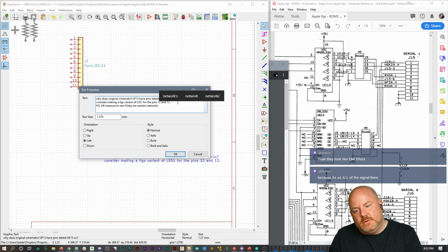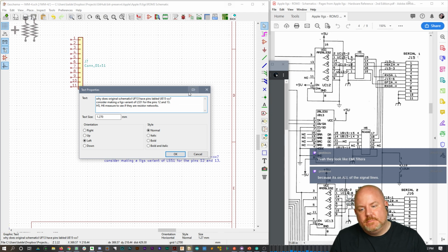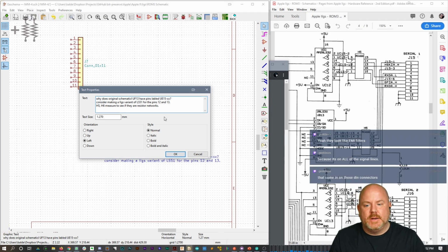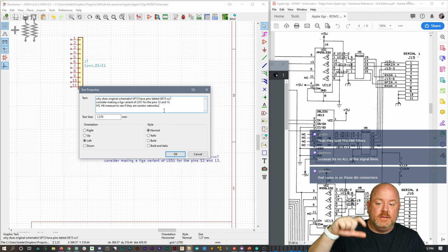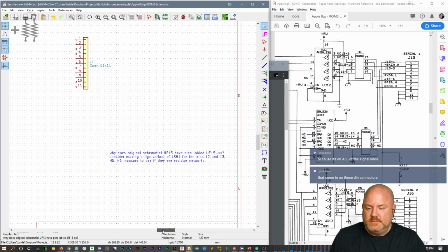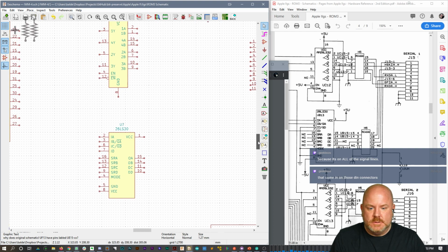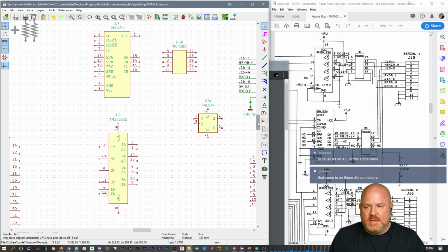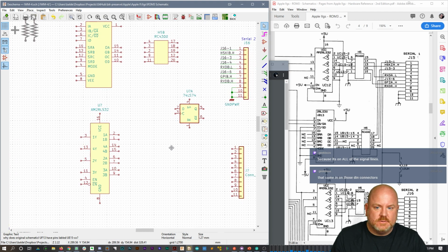I've already got my 2GS boards packed up, but I'll make this note so that when I take the board and I'm depopulating the other chips, I'll depopulate one of these and measure it and see if they seem like resistors. In fact, I even have a handheld LCR that I can use to verify if they have any reactance.